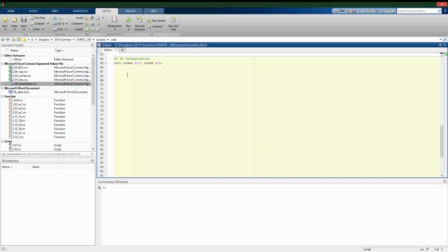Now you can see an example to use our 2D interpolation here. We have this data from 9 thermocouples measuring temperature on a plate at specified intervals across the horizontal dimension and vertical dimension of the plate. So our x locations are at 0, I'll just type these in manually, 0.5 and 1. And our y are at 0, 1, and 2 meters on this plate. Those are our independent variables. And our temperature at 0, 0 is 80, 100, 120, 120, 130, 135, 130, 142, and 149.